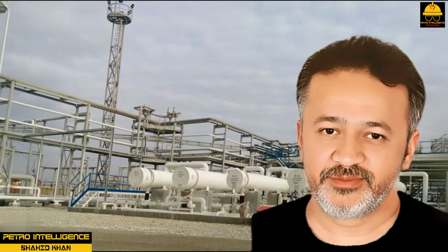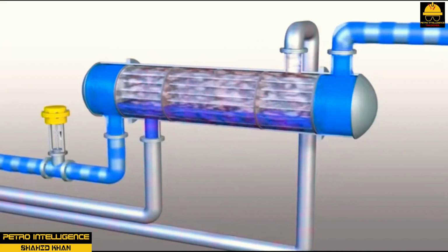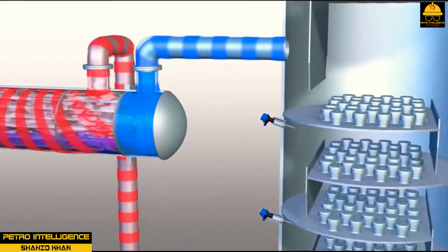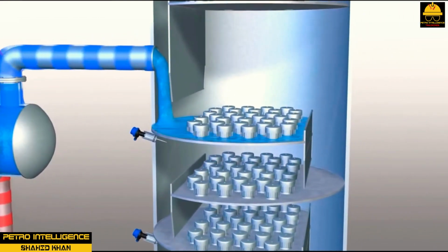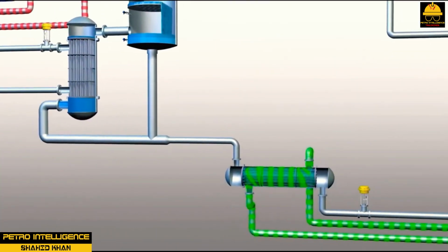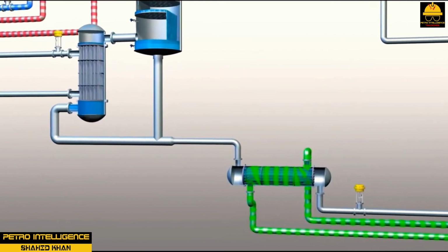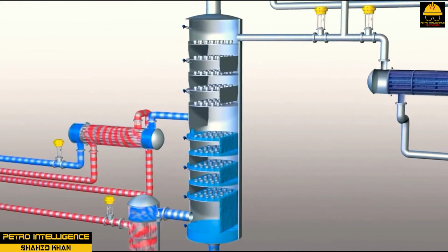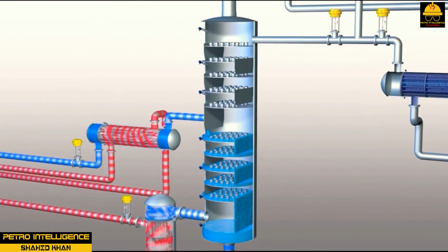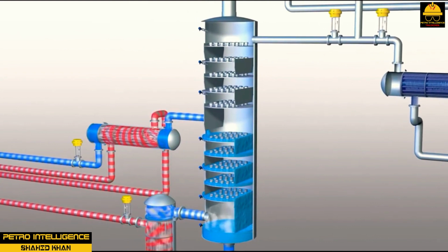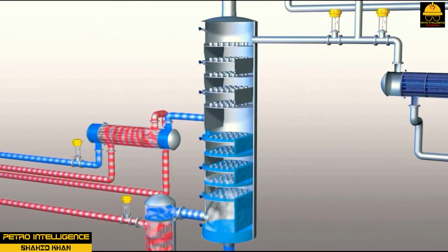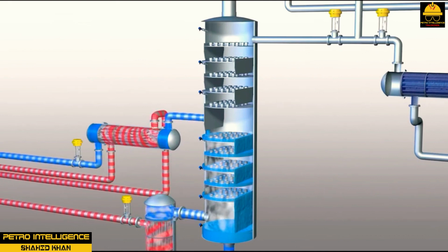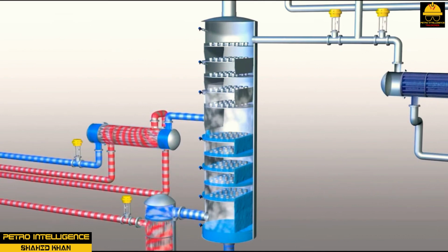Distillation columns. Distillation columns use heat exchangers to preheat feedstock in heat exchangers, condense hot vapors in condensers, or add heat to the tower and crack or separate heavier components in kettle and thermosiphon reboilers. Condensers are typically shell and tube heat exchangers used to condense hot vapors into liquid. A condenser can be found at the top of most distillation columns.